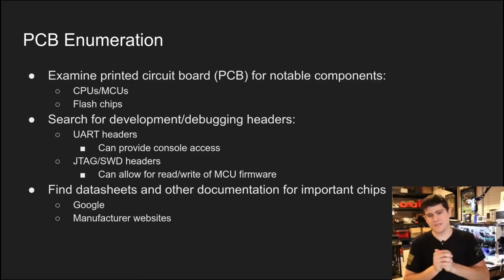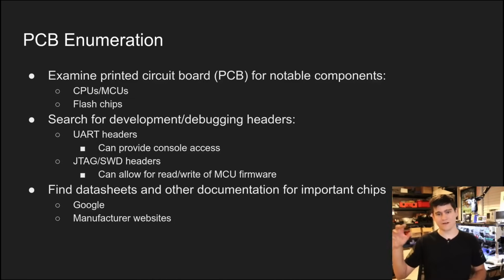So the first thing that I do when I open up a device, I want to identify all of the important chips, the important components on that circuit board. So we're looking for, again, the CPU or the MCU, and that's where you start to find out when you open this device whether it is a microcontroller type of system, or is it going to run Linux or Android, something heavier? And then you're also looking for flash chips, right? Where data is stored in a discrete chip that can be read with a number of programmers.